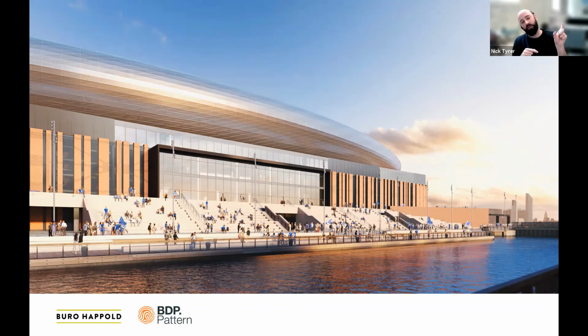And you might think, oh well, it's just 5,000 extra seats, but those 5,000 extra seats are at the top of the bowl, which means however big the bowl is, you're adding another 4 meters of height onto a building. You're making the building wider, it might be 4 or 5 stories up, it makes the roof longer. So yes, it's 5,000 extra seats, but what are the changes in the span of the roof, what are the changes to the area of the facade? All these are things that are quantifiable and that we can take out. And so we've done that before.